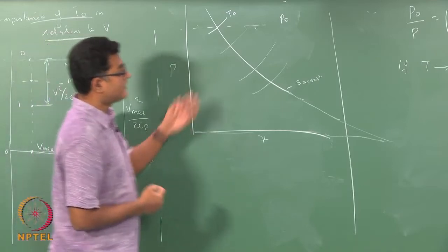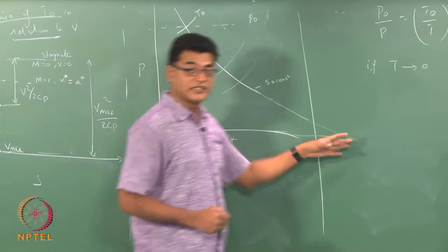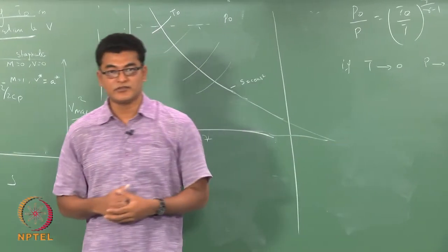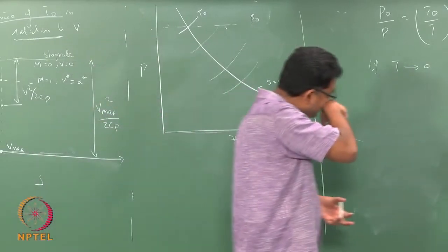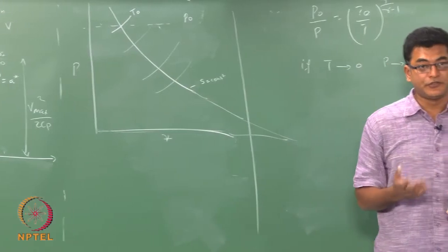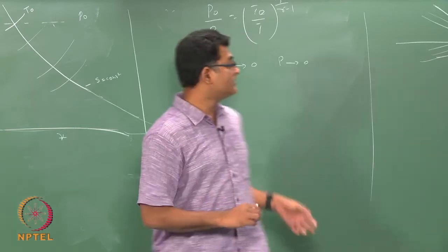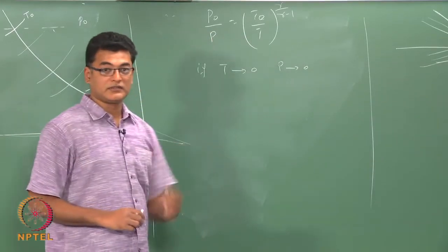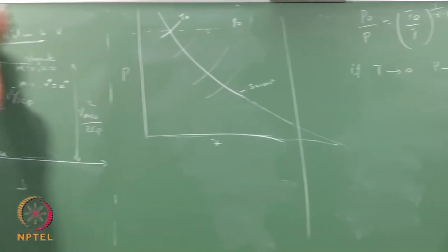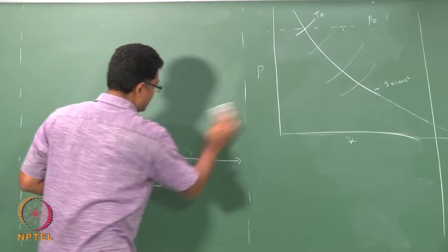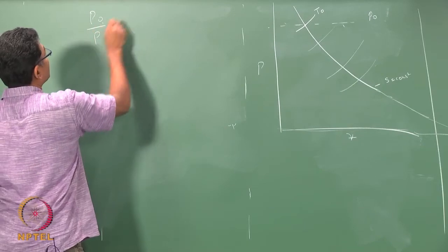Okay. So, if I have a large stagnation temperature, I can get an associated Vmax, which is my new reference quantity. Now, before coming to the quantity variations due to area change, which is what we have been doing in the last few classes, we will see how this essentially varies with Mach number, which we have derived to be of this form.